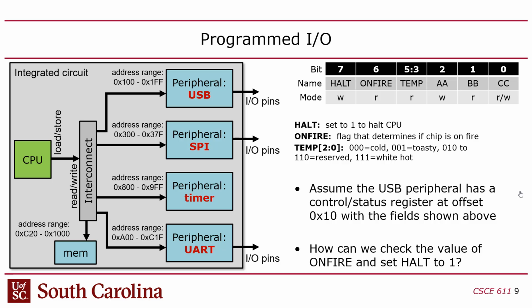Like I said, it's not that hard conceptually, but when you have to do this a lot, it's error prone and kind of hard to debug. And this is what I was talking about, by the way, with the debugger. On our old board, we didn't have a debugger. So, for example, in order to interact with the peripheral, you would have to read and write 27 different bit fields from 10 different registers. And if one single instruction was wrong, brick. You bricked it. It does nothing, right?